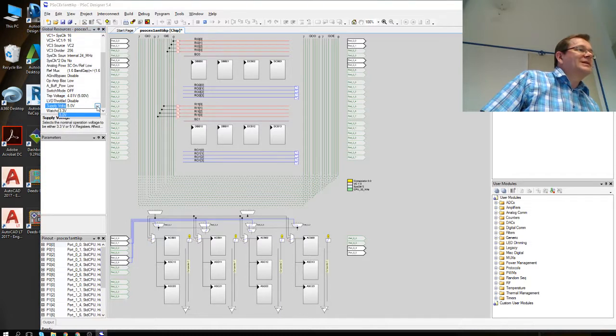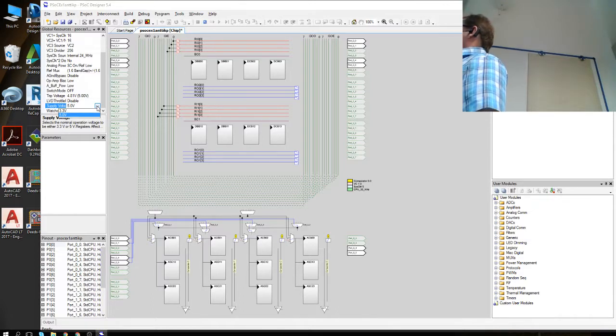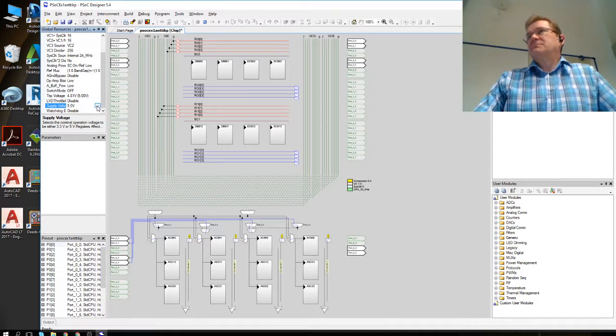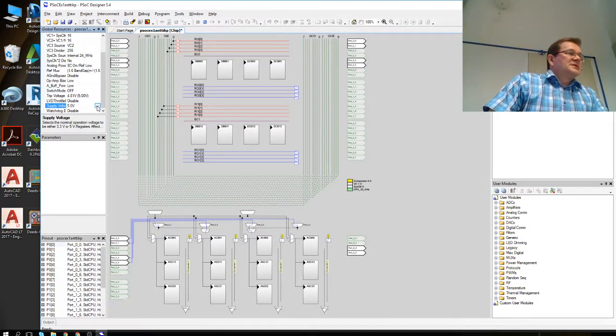And supply voltage actually is either 3.3 volts or 5 volts for this device. And we're using 5 volts because this one gives 5 volts. On a lithium powered system, you would put the 3.3 there. And that voltage, of course, doesn't need to be exact. It just sets some parameters for the system, so it's optimized for that range of operation. So there's quite a big tolerance on the supply power.